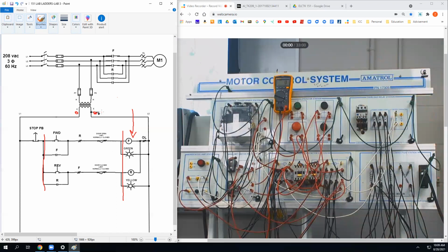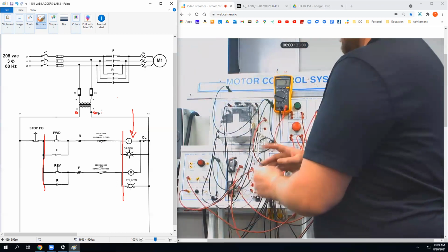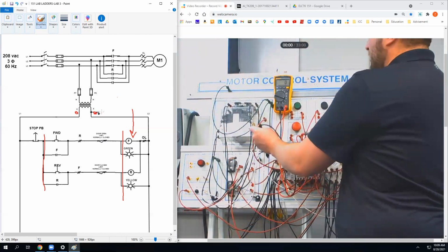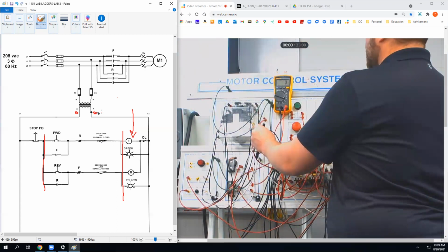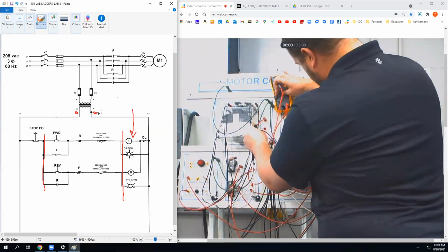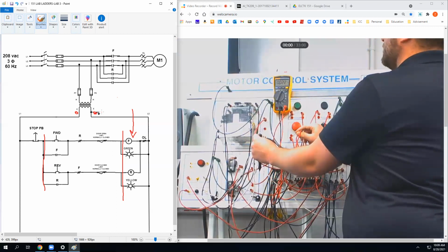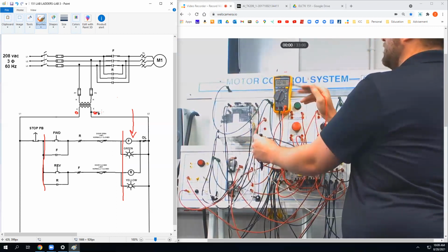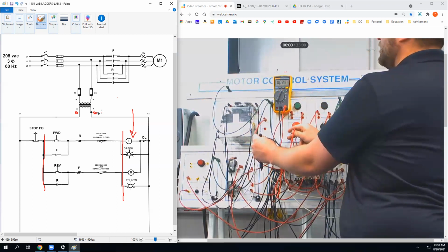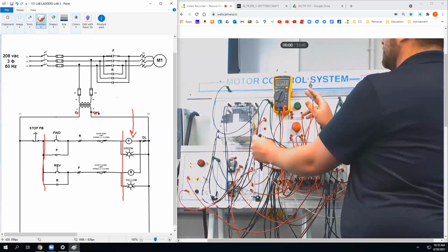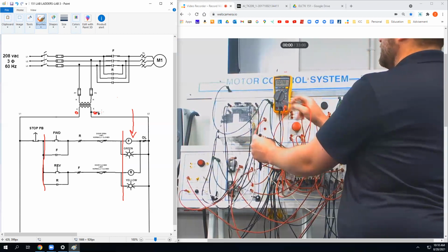Okay, so what did we decide we're going to check here? Load side push button. Yep. So I'm checking the 2. I'm going to go load side of the stop push button. That's continuity. Nothing. Should I check the line side? Yeah. Nothing. What should I check now? You check the line side? Yeah. What do you get? Got 0. Okay, when you go back to the load side transformer. Load side of transformer.